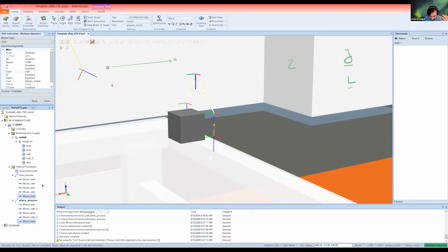we are using Move J. Move J means that the robot is going to find the most efficient way to reconfigure its joints to get from point A to point B. That means the TCP, or the end of the tool, for example the head of this pen, may not move along a linear path. It may actually make a move like this to get from here to here. The whole body of the robot is going to move around, but the TCP may make this motion, and it is really important.